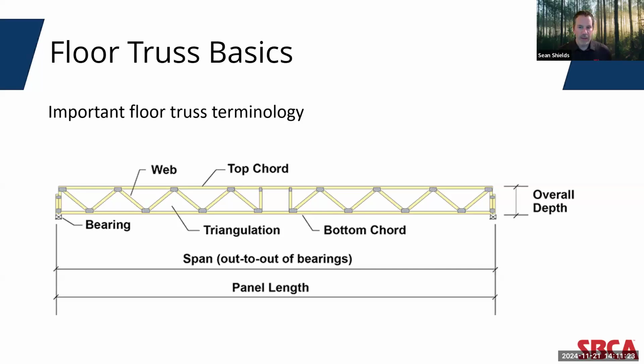Typically, floor trusses have webs arranged in a pattern to maximize triangulation of compression and tension forces that allow the truss to span large distances. There are also perpendicular webs used at bearing locations and at chase openings. Over the bearing locations, these perpendicular webs allow for efficient transfer of forces directly from bearing walls above the truss into the bearing locations below them. For chase openings, these rectangular or square openings allow for easier installation of HVAC mechanicals, plumbing, and electrical infrastructure.